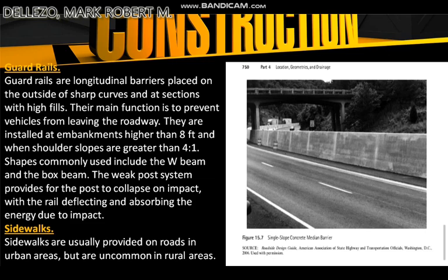The weak post system provides for the posts to collapse on impact, with the rail deflecting and absorbing the energy due to impact. Then the sidewalk. Sidewalks are usually provided on roads in urban areas but are uncommon in rural areas.